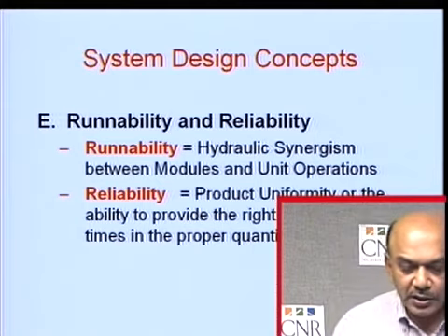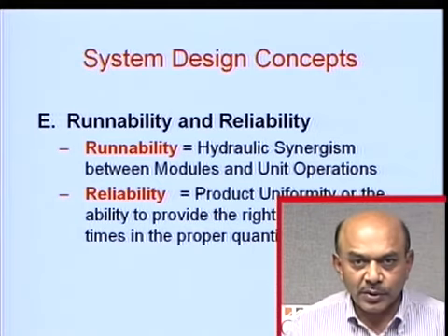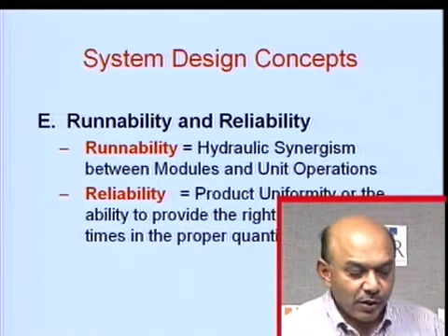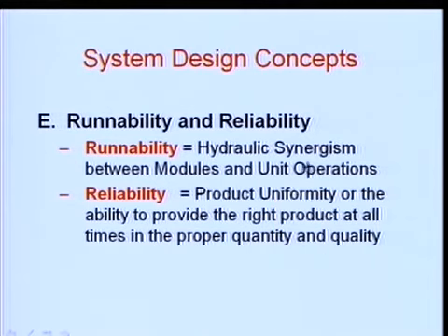However, all these things must be put together in a sequence so that you have what you call hydraulic synergism between modules and unit operations, and this is runnability. As you maintain hydraulic synergy between each module and each unit operation, you're better off. In other words, as you pass from one module to another module, the consistencies and the flows and the temperatures are all in sync with each other.